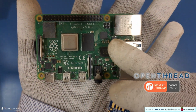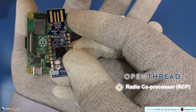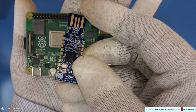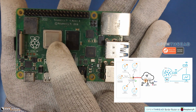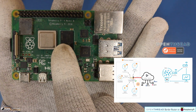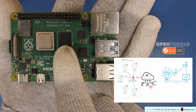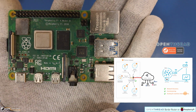Raspberry Pi as an OTBR or OpenThread border router, and Nordic's nRF52840 dongle as an OpenThread radio coprocessor, the RCP unit. The RPi acts as the central brain, running the OpenThread border router software that connects the low-power Thread network to your home's Wi-Fi or Ethernet network. It handles the higher-level network logic, such as IP routing and network management.